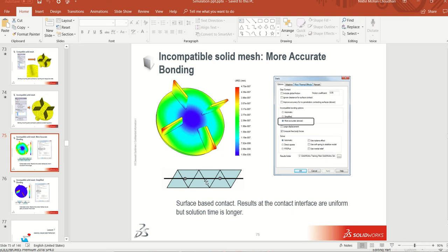These two elements are there but a node is not there, but it will consider those elements as well. So for calculation purposes, at the touching faces, however many elements are there, that whole is going to be considered. Because of that, the calculation time is greater than the simplified bond image, but your result is more toward accuracy.